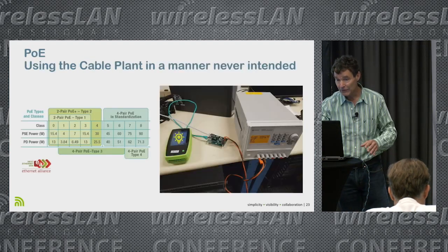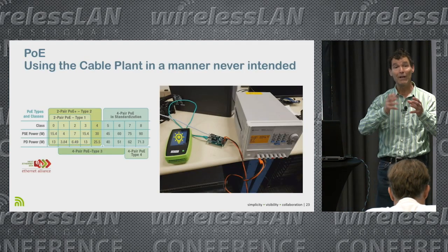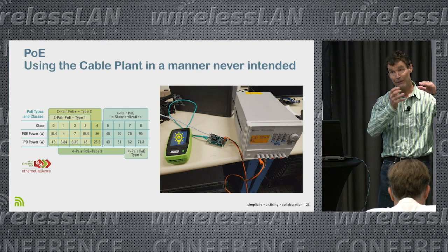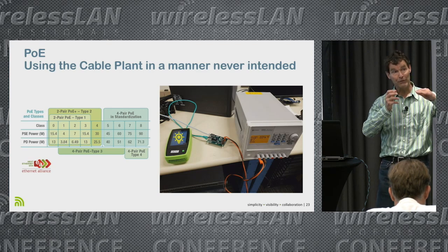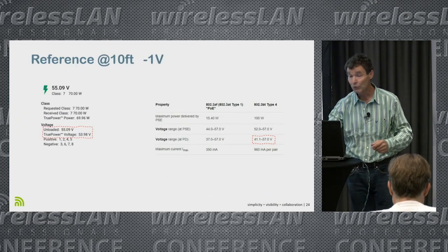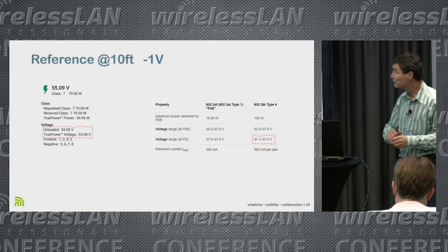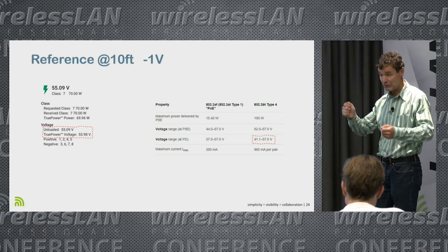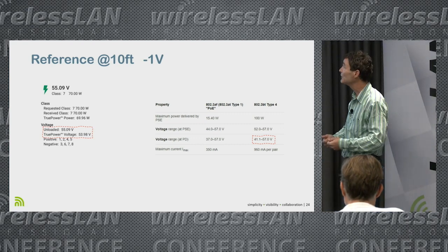The other thing I should say is in our products we have the equivalent of a light bulb. So we measure the voltage, we plug the light bulb in, then we measure the voltage again, and that's the voltage under load, right? It's kind of like starting your car on a cold morning. The battery can read the voltage, but when you go to turn it over, the voltage drops.